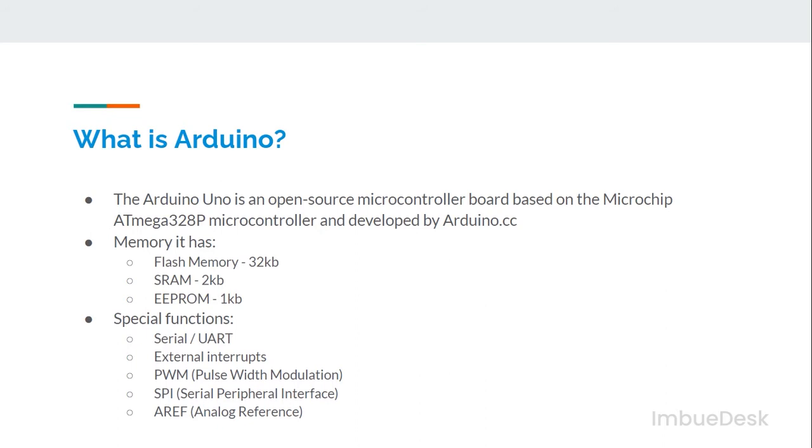A microprocessor uses an external bus to interface to RAM, ROM, and other peripherals. On the other hand, a microcontroller uses an internal controlling bus. Hence, an Arduino is a microcontroller which has an ATmega328P microcontroller with general purpose input-output pins. Using Arduino, we can do many things and we will do a few projects in this course. So those are the specifications of an Arduino.